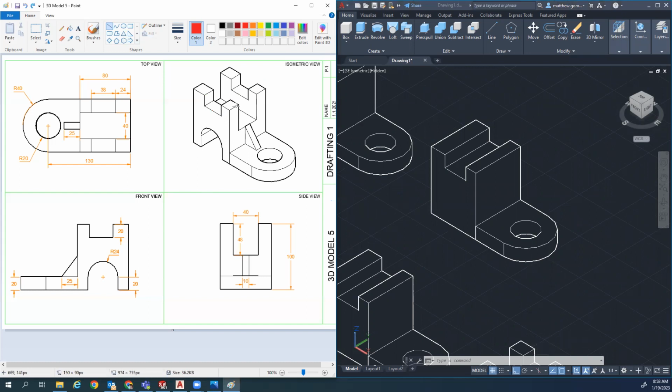The same thing applies for the next step, except we need the dimensions of this box. We're imagining a box right here, and we're going to press pull it back this direction. So I need to get the size of that box. This 40 is the width. This 48 is the height. Now I need to get it in the middle. So I also need to know how far this is right here. If the total length of this was 40 and 40, which is 80, so the total length of that whole line right here is 80.